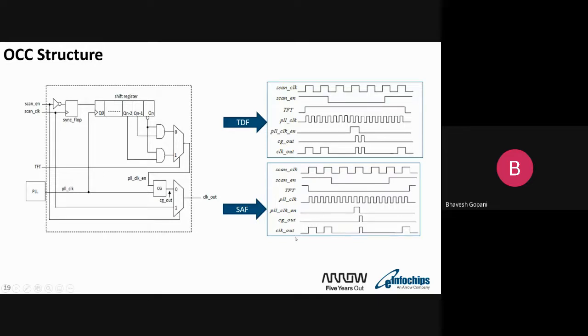If I want to test a stuck-at fault, only one capture pulse is enough, because I am placing the data in a flop with shifting and directly doing the capture at any frequency, because there is no transition. So I'm not checking delay related issues here. My intent is only checking logical faults, either stuck-at 0 or 1 due to some manufacturing defect.